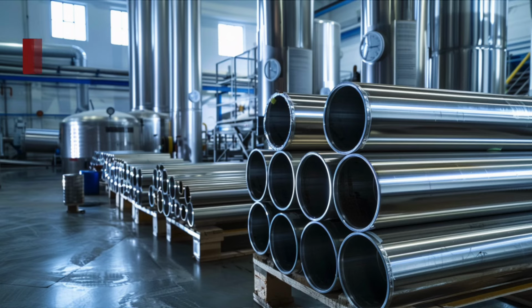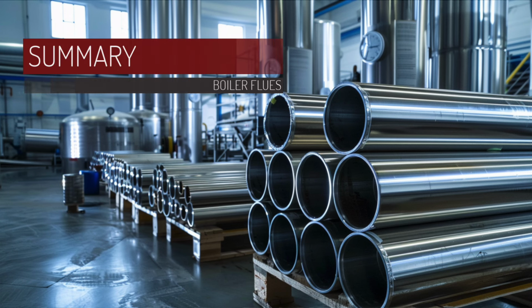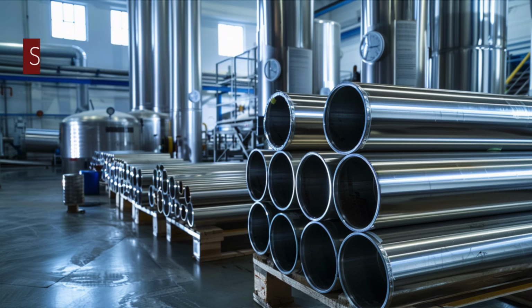Summary: when replacing a non-condensing boiler with a condensing boiler, it is essential to thoroughly assess and potentially modify the existing flue system to accommodate the specific requirements of the condensing boiler. This includes using appropriate materials, ensuring proper sizing and configuration, managing condensate, complying with codes and regulations, and potentially insulating and sealing the flue system.